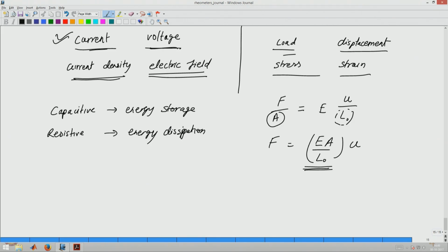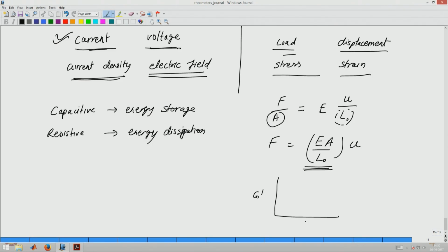So, for example, just the way we saw that the basic primitive model for viscoelasticity was the Maxwell model, right, which said predominantly viscous response at low frequencies and then elastic response. Then we saw also the standard linear solid model, which was elastic response, which was rubbery, and then elastic response, which is glassy. So, what we saw was G prime as a function of frequency was something like this. So, at very low frequency you get rubber elasticity, at very high frequency you get glassy elasticity, and G prime varied like this.